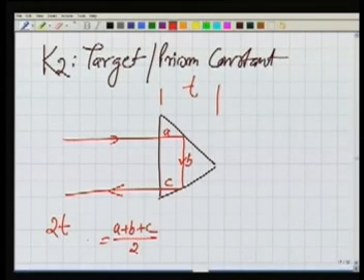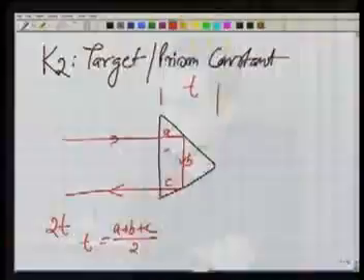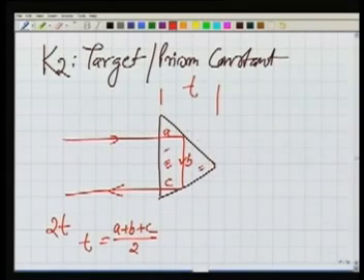will be t. Now there is a little problem. This is our target, meaning the one in which the prisms are there. This is the glass, and for this glass the refractive index is different from that of air. In air our EMR travels at a certain velocity, while in this glass material the velocity changes, and because of the change in velocity we need to apply a correction.